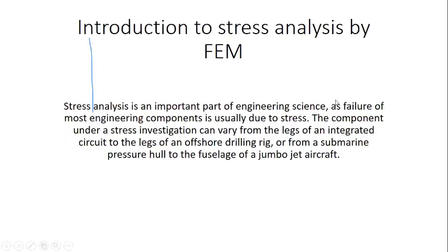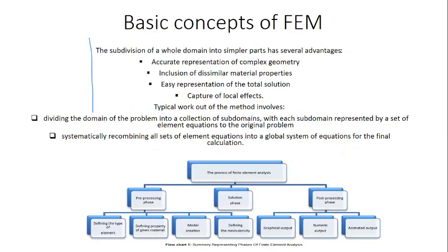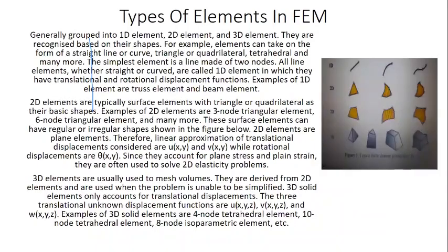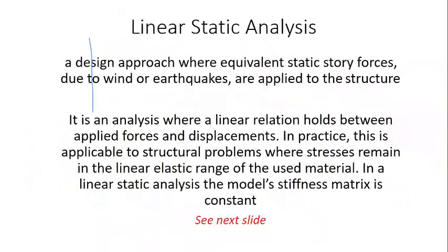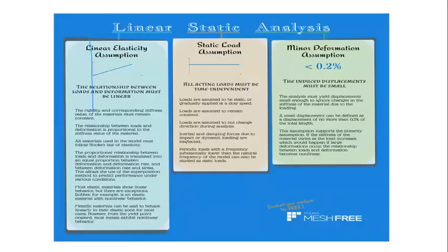All right, we had an introduction to stress analysis. We looked at the basic concepts of finite element method or finite element analysis. We looked at 1-dimension, 2-dimension, and 3-dimensional elements. We also analyzed linear statics, which is an analysis where a linear relation holds between applied forces and displacements.